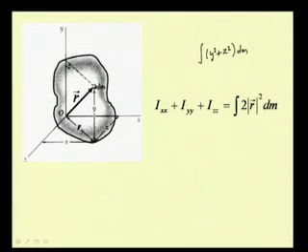In the same way we add up the other quantities, that is integral x square plus z square dm plus integral y square plus x square dm, which is nothing but 2 times x square plus y square plus z square, which is equal to the magnitude square of this vector r. So, that is what we write as integral 2 times r bar's magnitude square.